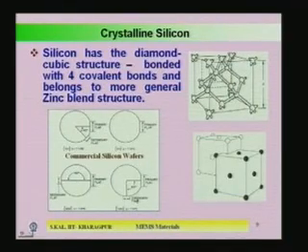In the case of MEMS devices or even VLSI devices, the normal wafer we use nowadays is mainly the 100 silicon wafer. There are certain advantages of that. The main advantage is that 100 silicon can be cut into small pieces in a regular way, because whatever devices you make, either a VLSI chip or MEMS, at the end you have to separate the chips, you have to break the chips. So, a 100 wafer can be broken in a regular fashion